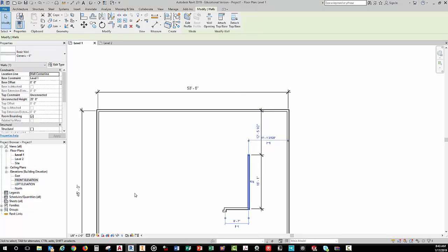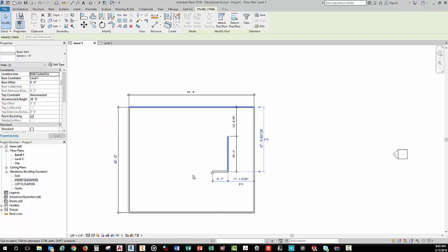You want to pick the object that you want to edit, and then you want to pick the dimension that's highlighted. And if you have more than one thing, like if you hold down Control and add something to your selection, so Control adds, and if I hold down Shift, I can deselect. So to add things to my items, see, I can pick these 2 items there. Notice my dimensions turn back to black, but I get activate dimensions up here in the top left. So I can click on activate dimensions, and then it's going to give me dimensions that I can adjust. Like, oh, hey, there's a dimension that I can mess with.